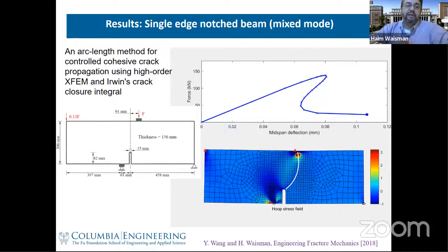That's why, in my opinion, in that sense, damage mechanics is a more physical approach, because then you can calibrate your damage model directly to a behavior that one will have. But again, because of numerical issues, damage mechanics will have problems, right? And so one approach in damage mechanics would be to use what is called non-local damage models to address that.